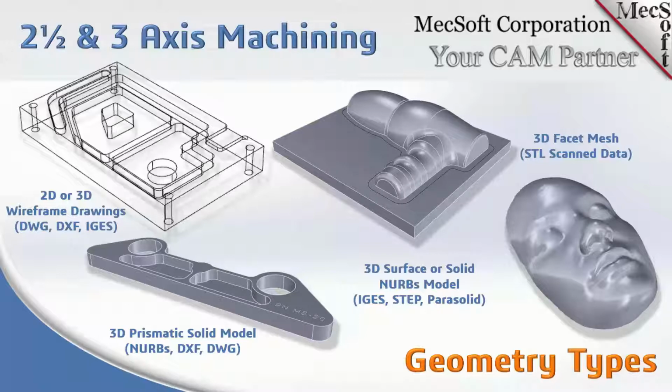If you're going to work in 3 axis, you do need to have a part model. You need to at least have a surface. It doesn't have to be a solid. You can machine just a single surface in 3 axis. Typically, though, you'll have a poly surface or a group of surfaces, or a closed poly surface, which is actually a solid model. So you can use solid models, open poly surfaces, etc., for 3 axis. Now, in the bottom left part, you can use 2.5 axis methods on a 3D solid as well.